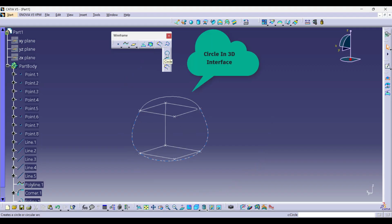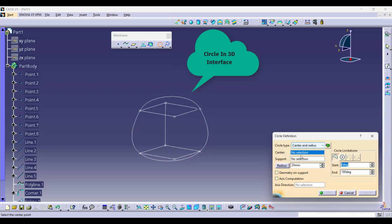After that we are going to see the 3D circle. If I want to make one 3D circle, I can go for that also. You just need to select the circle command. It will ask you for one vertex point or center point. So I'm going to select this corner as the center point. So this corner has been selected as the center point.